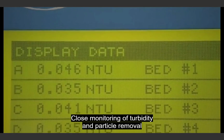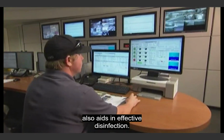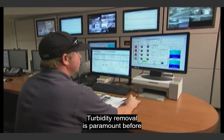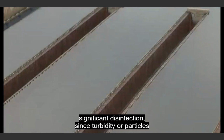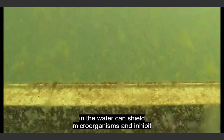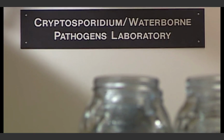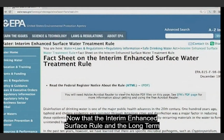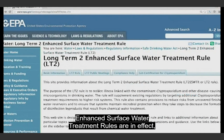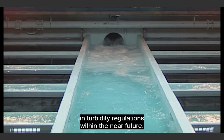Close monitoring of turbidity and particle removal also aids in effective disinfection. Turbidity removal is paramount before significant disinfection, since turbidity or particles in the water can shield microorganisms and inhibit chemical disinfection from inactivating the pathogens. Now that the Interim Enhanced Surface Water Treatment Rule and the Long-Term Enhanced Surface Water Treatment Rules are in effect, odds are that there will be minimal changes in turbidity regulations within the near future.